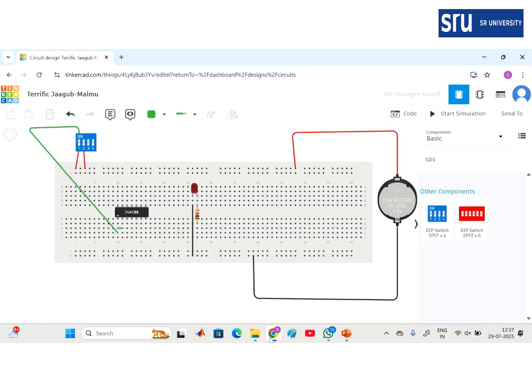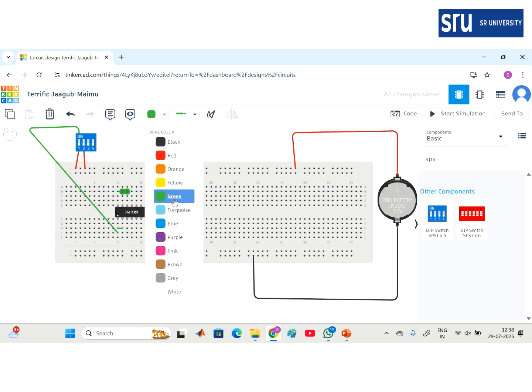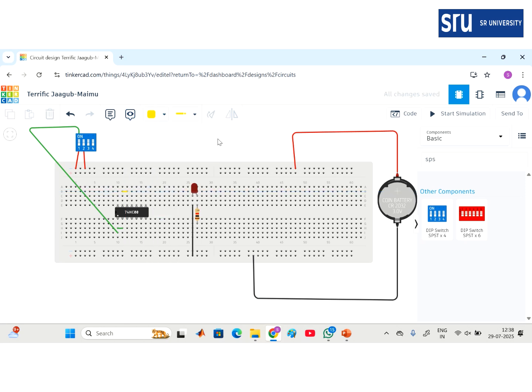Right. So A bar is the first output, that is A bar, the first output of the first NAND gate. Now again I am using the 4B and 4A. Now again short circuit 4A and 4B. For differencing, I'm using different colors for different inputs.